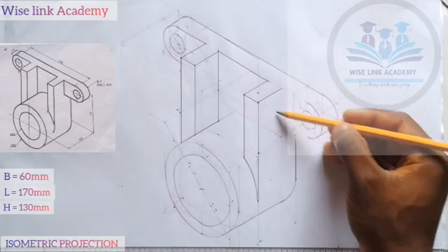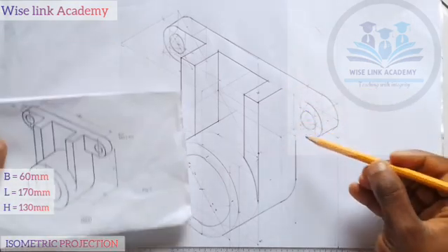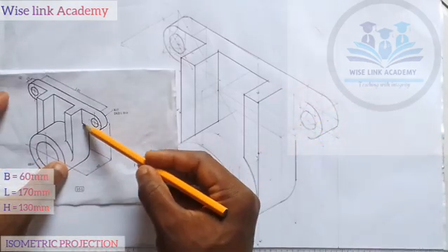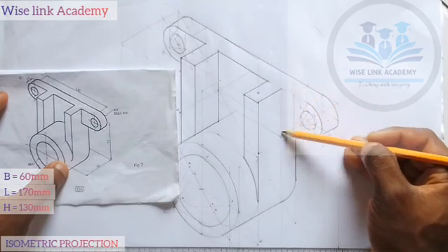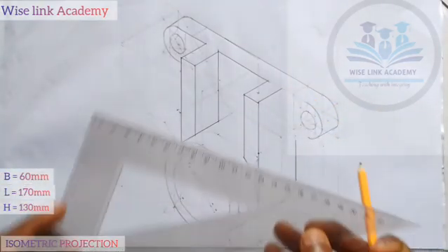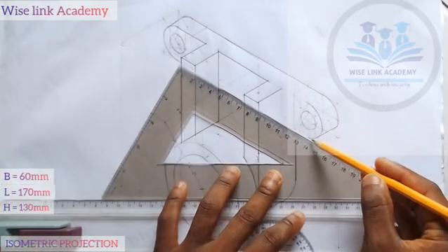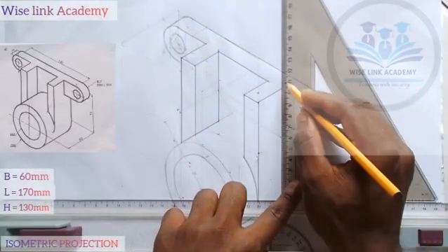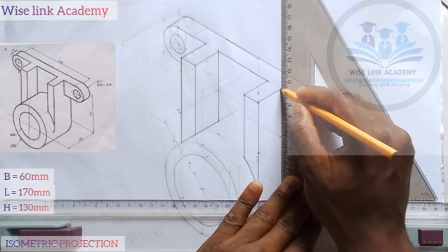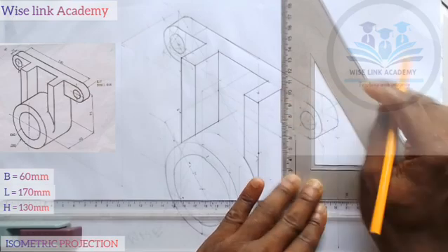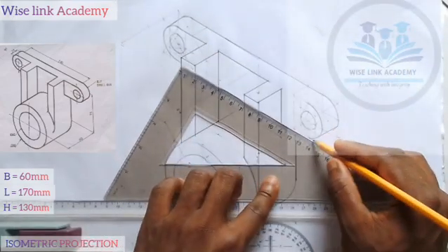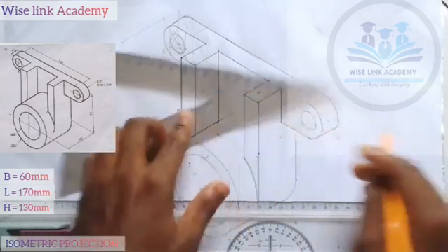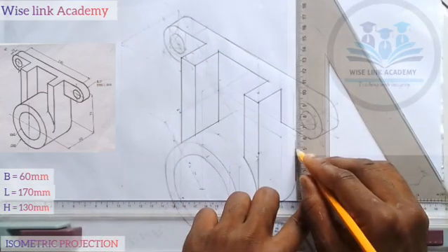connection here, right? See, listen, there's a straight line here and a straight line down here. A straight line should come down here. So how would I do that? I'll take my T-square this way. This point here, extend it down. So just take this one down where it touches that point. This point here, take it this way. Also, I will close this guy this way and take this point up finally this way.